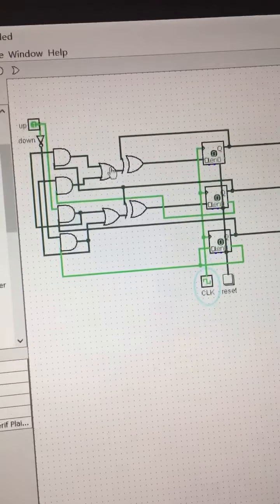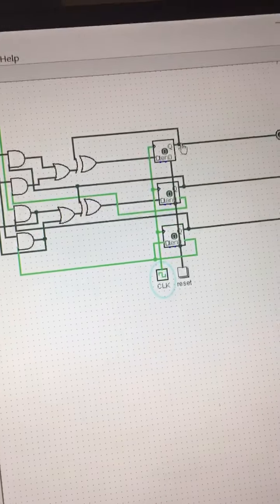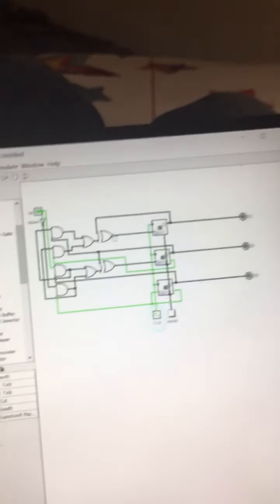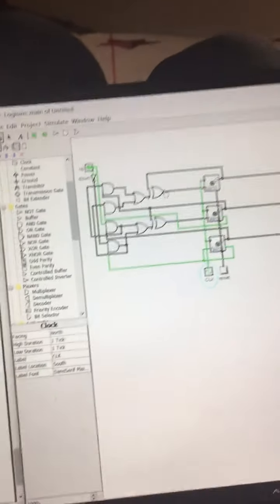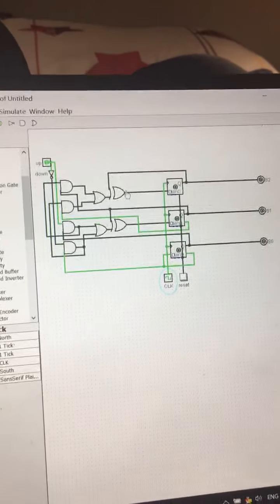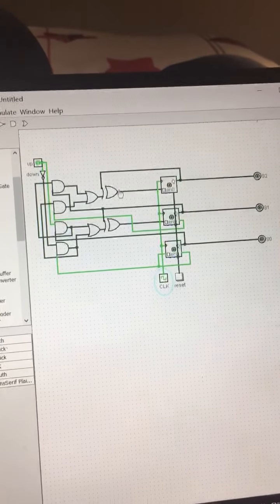And with a similar process, you do an OR gate, and then you do an XOR gate that compares it with the current output and then changes it. So that's how it is. I think I explained it slowly, but basically that's how this circuit works. I drew it a bit messy, but you can see quite well what it is doing.